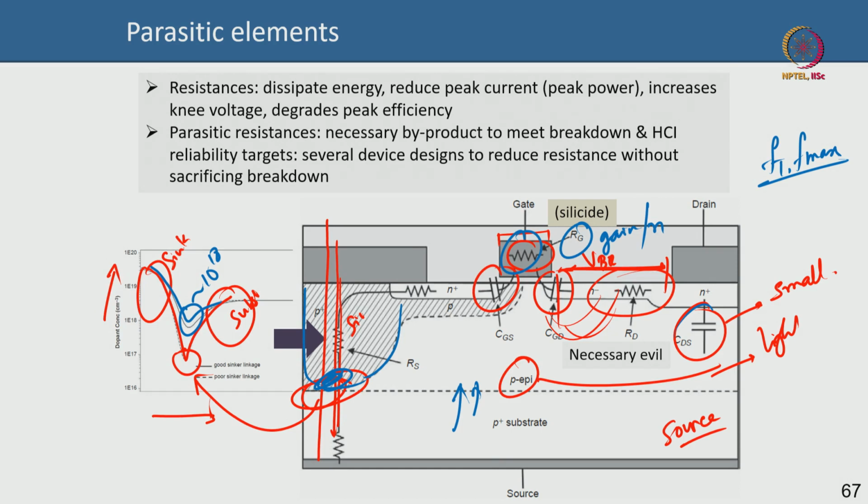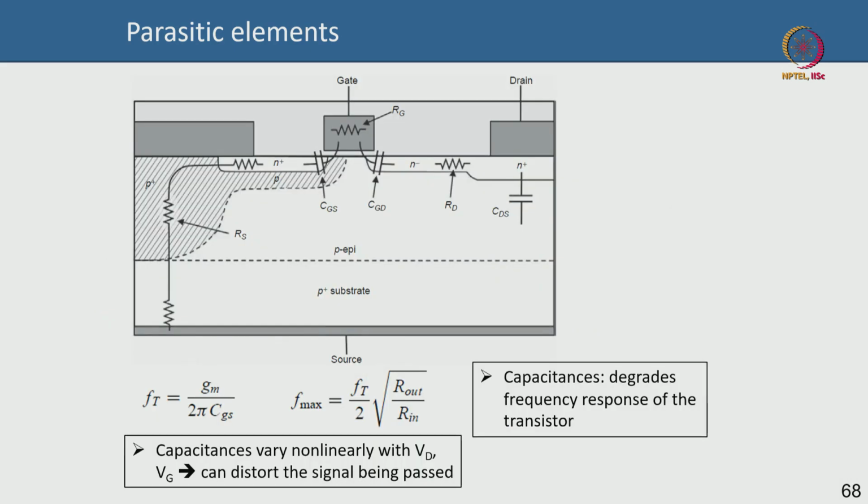So, cutoff frequency can be really affected by capacitances, okay. It can even completely kill the cutoff frequencies, please remember that. So, a very simple expression for FT, of course we have discussed this many times, so I do not want to repeat that, GM by CGS, okay, and it is basically the intrinsic FT and it directly depends on the velocity of saturation.